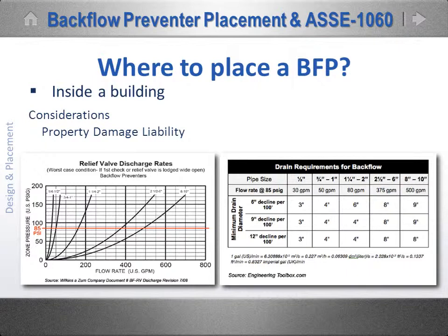And if you remember your fluid volume tables, and I'm sure you all do, you'll recall that a 4-inch drain pipe with a 6-inch fall per 100 horizontal feet evacuates clean water at a rate of 93 gallons per minute. If that device is flowing at 375 gallons per minute and you're only clearing 93, then you are flooding at a rate of 282 gallons per minute.